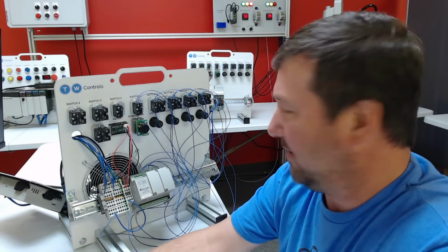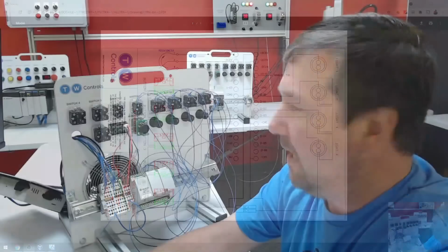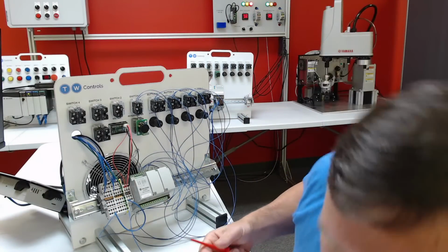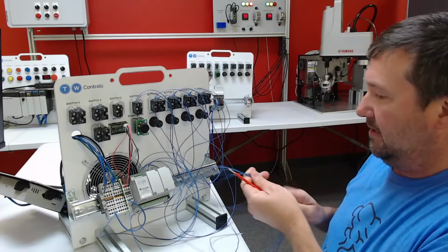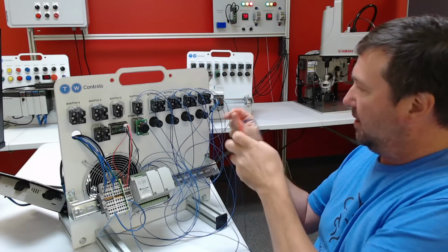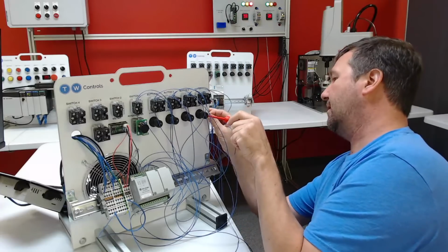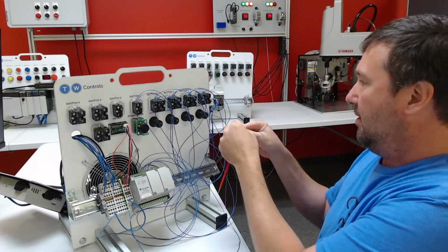All right, so that takes care of all of our input wiring here. So now we need to wire our outputs, and I'm just going to start by doing these jumpers to one side of each of our lights and going to the minus DC. On these particular lights, it doesn't matter plus and minus, so I'm just going to arbitrarily start connecting on one side and just keep jumping. So I'm going to take one wire to the right side of my light, and then I'm going to take it and an additional wire to light 2.